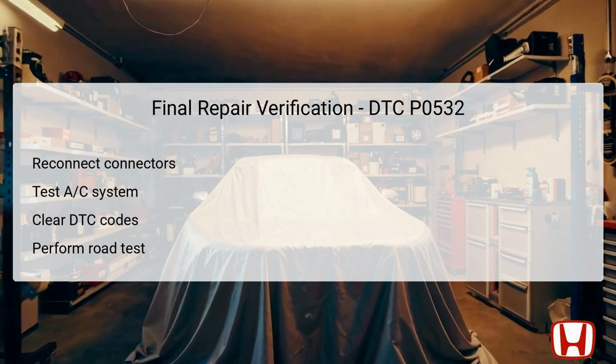Clear the DTC codes from the ECM using the HDS to reset the system and remove any previous fault indicators. Finally, conduct a thorough road test, monitoring the AC performance under various environmental conditions to ensure that the issue has been successfully resolved. This step is critical to confirm the effectiveness of the repairs and restore normal functionality.